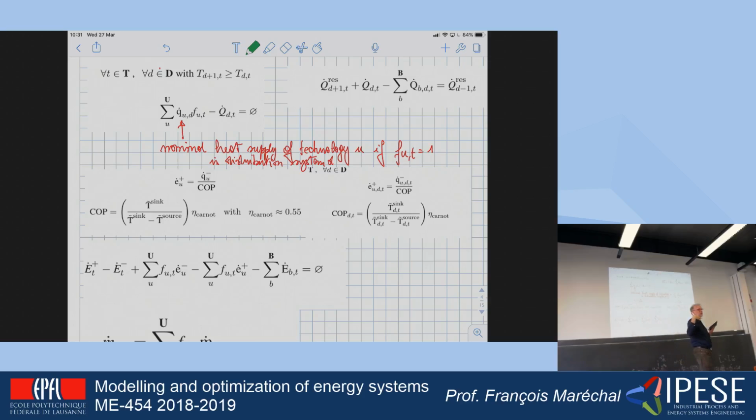But most probably they will not be as good as the maximum theoretical amount, because this is the maximum theoretical amount. I'm going to represent the non-ideality of the technology by using a factor which I'm naming the efficiency with respect to Carnot factor of 55. The value of 55 is just because I know that engineers are able to design systems that reach the 55 value here.